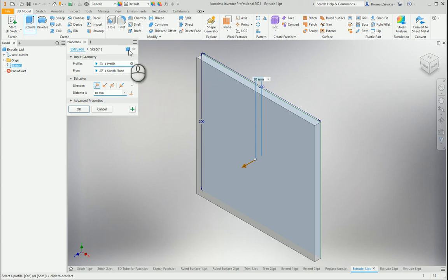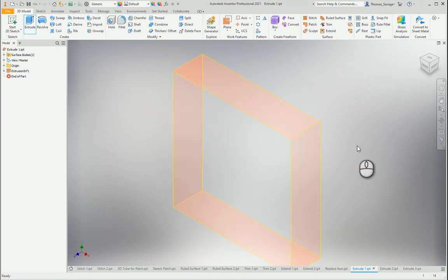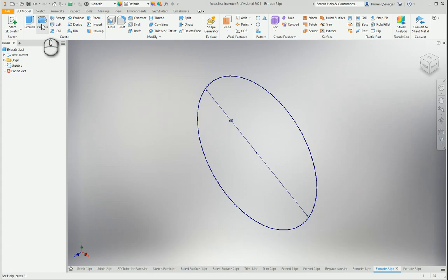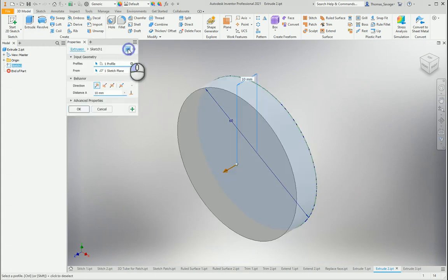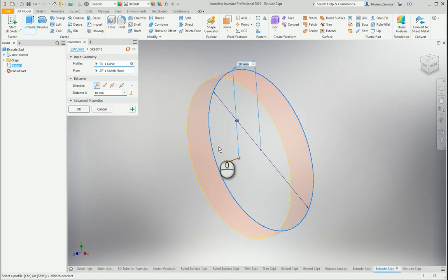So we click here, the solid box, which will then turn to extrude, distance 50mm. Okay, so now that extrudes that square, instead of making it a flat surface, it's extruded it out. And we can do it with a circle as well, which we've already shown. Again, it's just to show you can do it on any shape, and to get used to the change at the top as well.